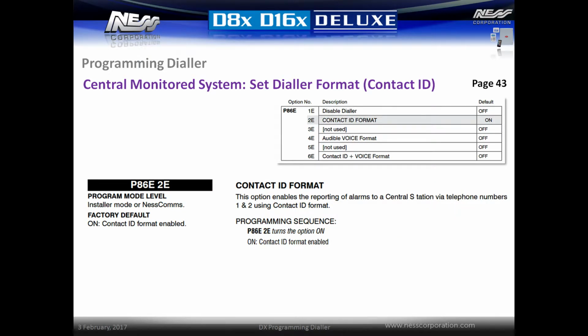The dialer format is set to contact ID by default. To check this, go to location P86E and ensure that 2E is selected.